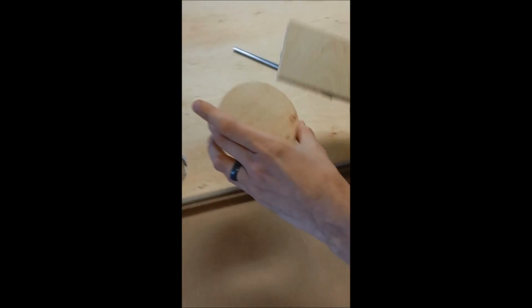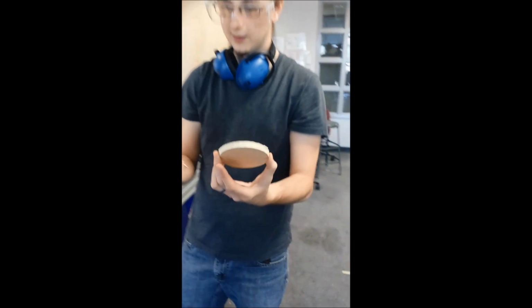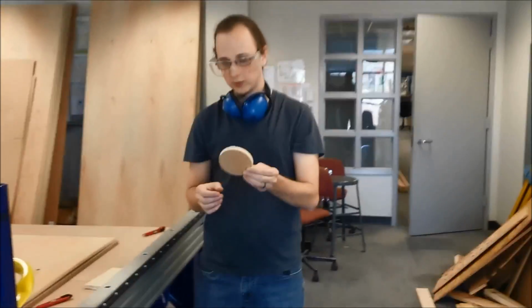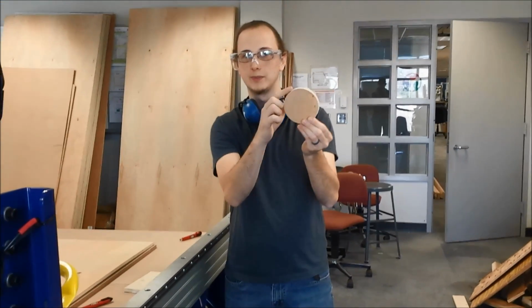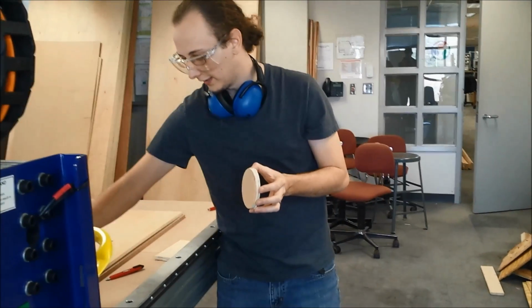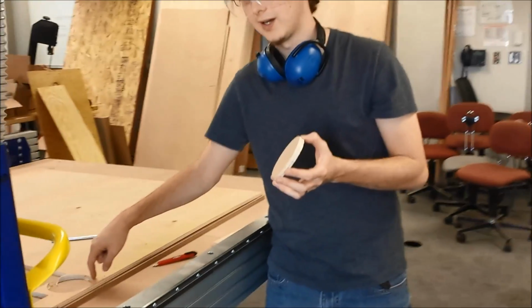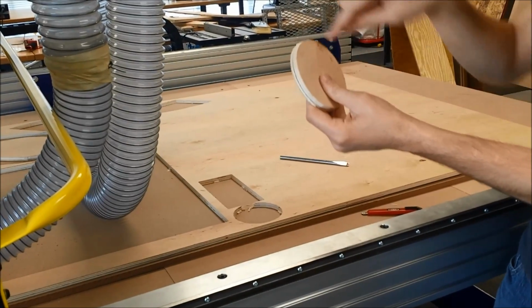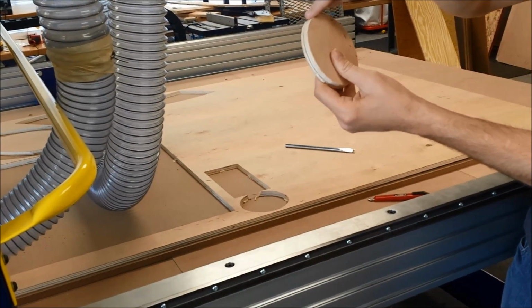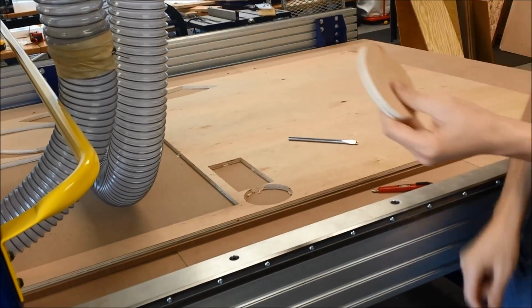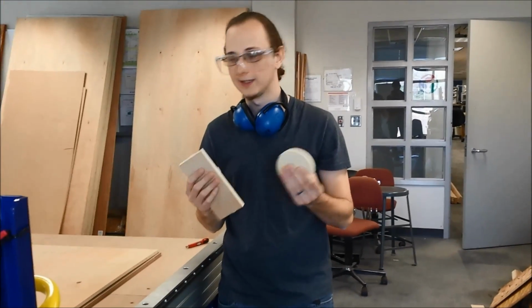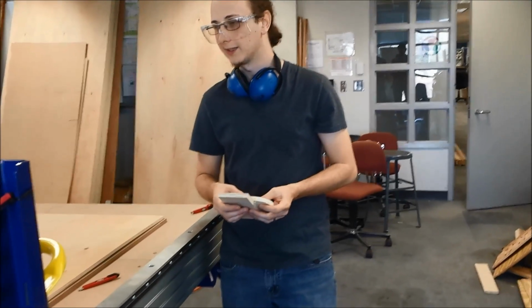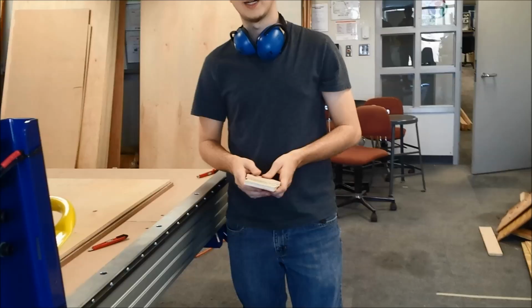And so now we have these two pieces that we designed in SketchUp and cut out. We just clean these edges up. The circle we made as a single path. If you look closely, it's actually still not a circle. It's made up of a bunch of little segments. We were able to cut a single long cut at once on the machine because we joined all those segments. Had we not done that, each one of these little line segments, the machine would have cut a little, then gone deeper, and then deeper still, and then it would move to the next one. That takes forever. So we're going to join all of our lines to make a complete line whenever we're cutting. But that's basically how you go from concept to physical parts.